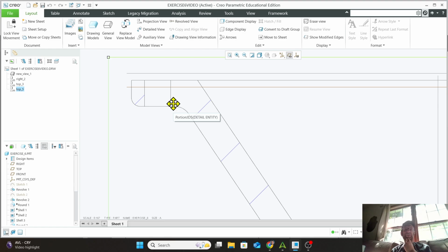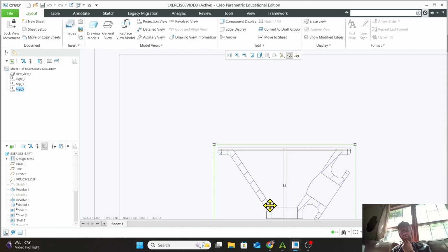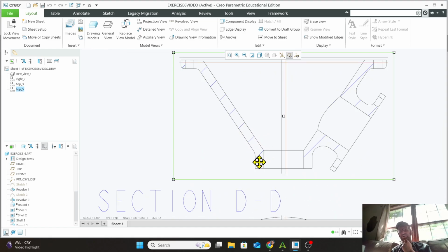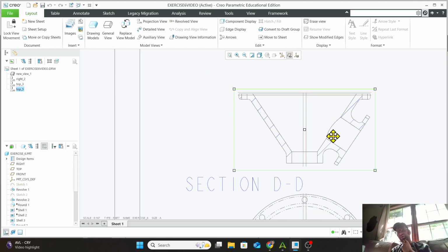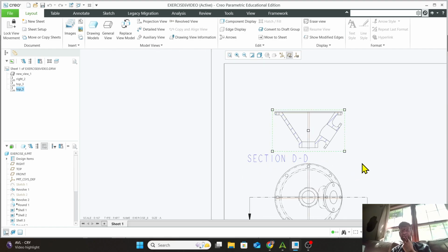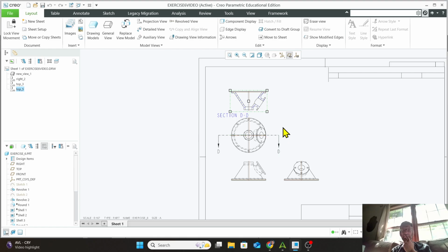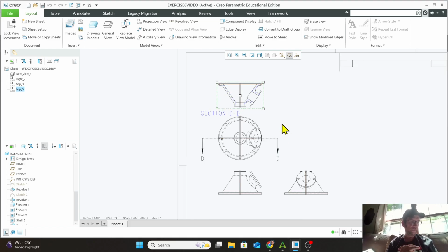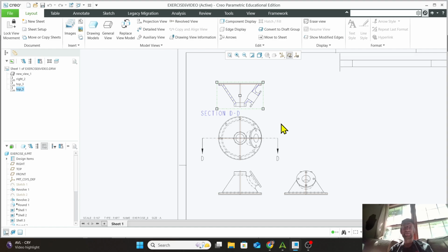Okay, we have object lines, which are black. So this is showing us a pass-through hole on here. We're showing solid material here, solid material on this side, all the way down and through to here, to the hole at the top, and then picking back up over here, hole in the middle there, and then solid here with a pass-through hole there and there. Okay, just so we kind of get an idea of what we're looking at, especially for those that are new, because it's a lot going on in this single drawing, definitely.